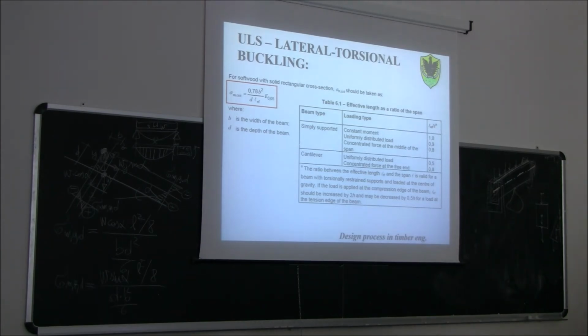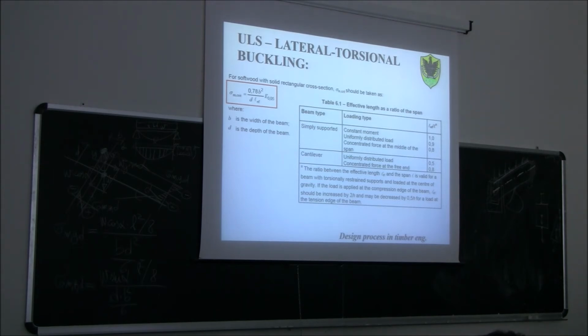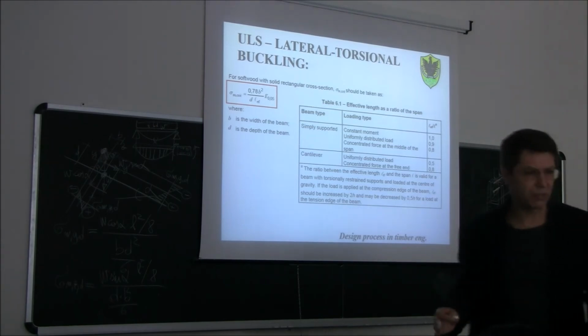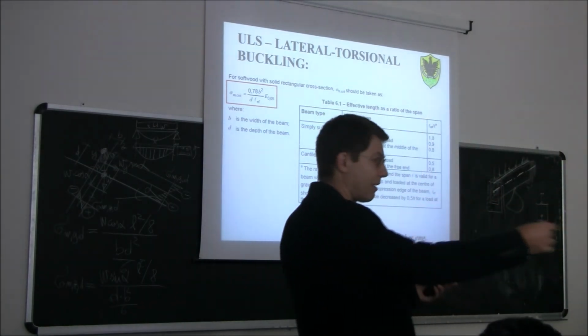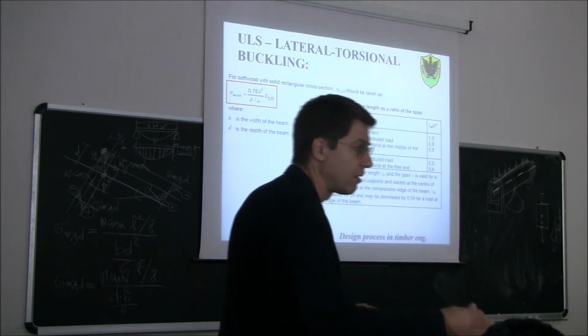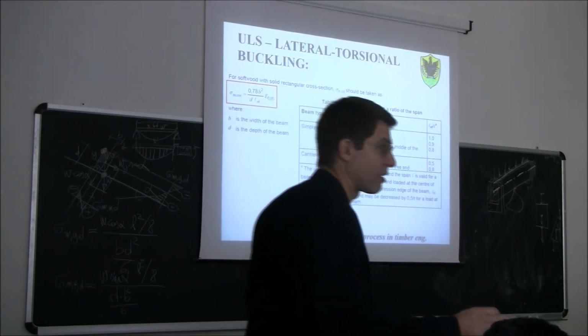The other thing I want to point out from the very beginning: when you have longer beams, like let's say a 15 meter long beam, there is no way that you can get this verification satisfied if you don't provide some lateral restraints along the beam. So this verification here is very critical for our structural method. You will see for a beam which is 22 meters long, if you don't provide any support, so any bracing, there is no way that you can get this verification satisfied.